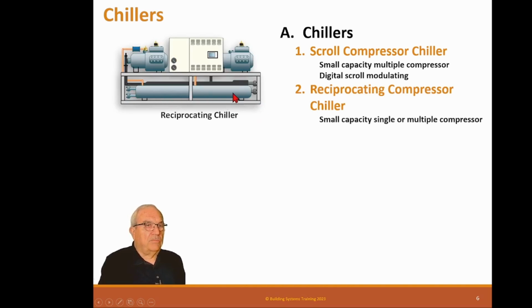This has got the chiller bundle, the condenser bundle down here, and they have these reciprocating compressors. These are semi-hermetic compressors, and they're called semi-hermetic because you can actually work on the heads. You can work on the valve plates without actually opening the refrigerant circuit. Now, the refrigerant actually cools the motor, so the motor's inside the compressor.